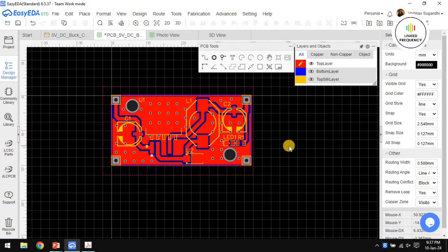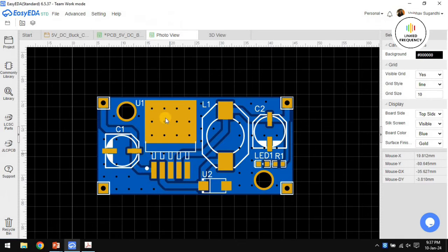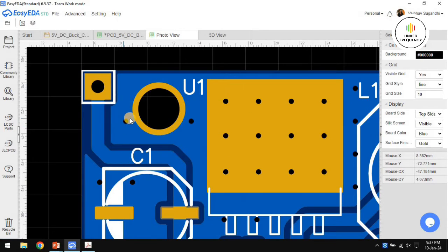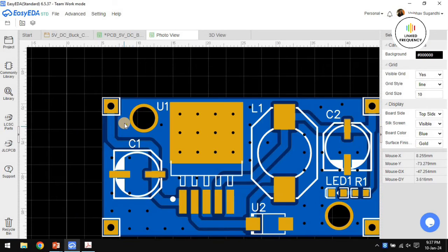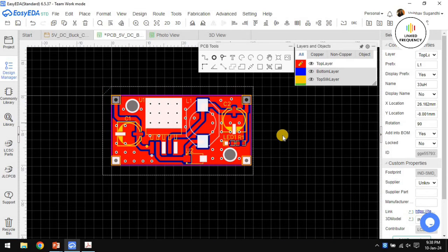These wires are tinted wires in the sense, if you go to the photo section, you will see that these are all normal wires only. They are not anything special. The normal wires which we use for the jumper, or which we use for creating a connectivity between the top copper ground plane and the bottom copper ground plane, the same wire I am using here. Because the pad is exposed, should be exposed, because we need to solder a body of the IC, right? Because of that, these wires are looking like untinted or not tinted wires. However, do remember, these are the normal wires which we are using.